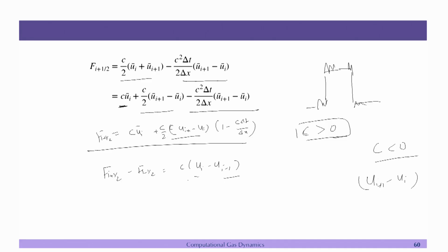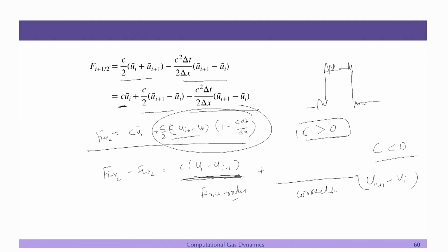So then you have this first upwinding part, and then these two parts which come up because of the correction in the upwinding. This is basically the first order, and then you have some correction which is coming because of this term, and we have to work on this part so that you get the higher order, and still we do not have wiggles.